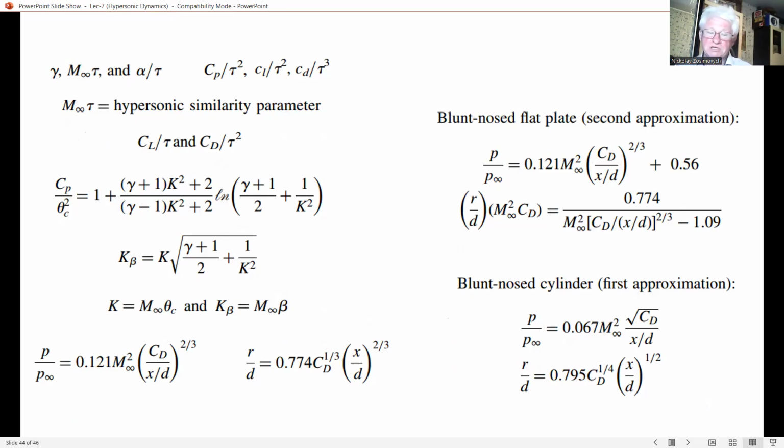The hypersonic small disturbance equations themselves can be directly solved for the flow field between the shock wave and body. In particular, the application to a cone was used here to illustrate such a solution based on hypersonic small disturbance theory.